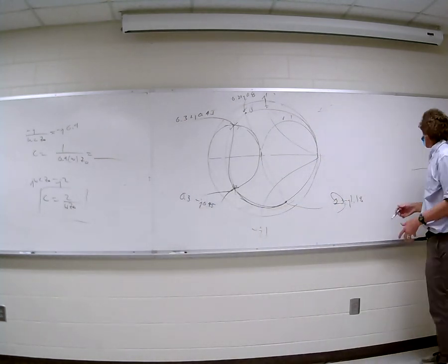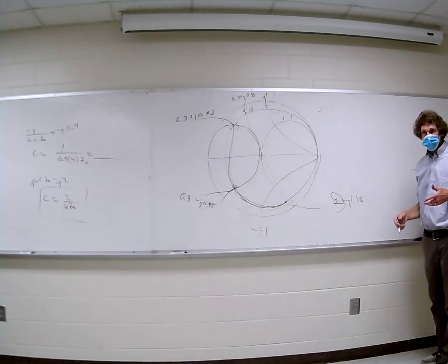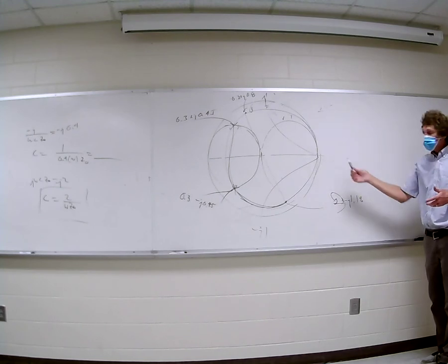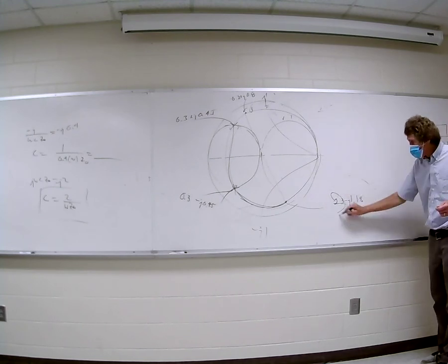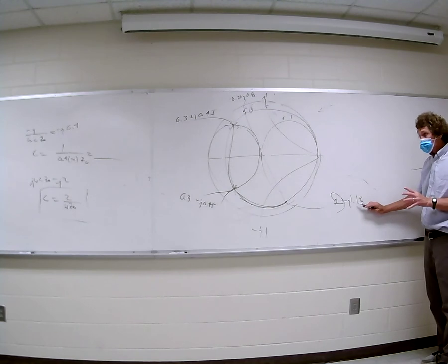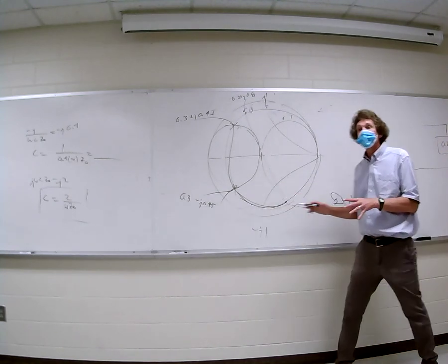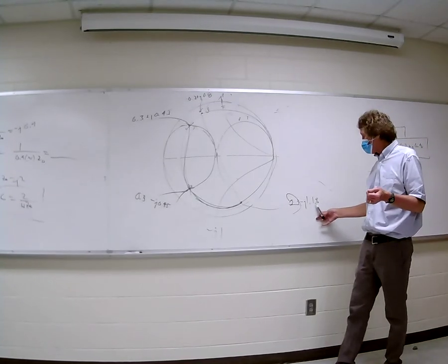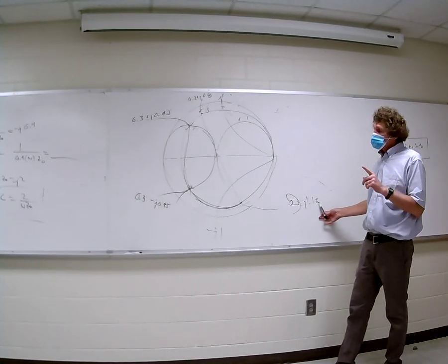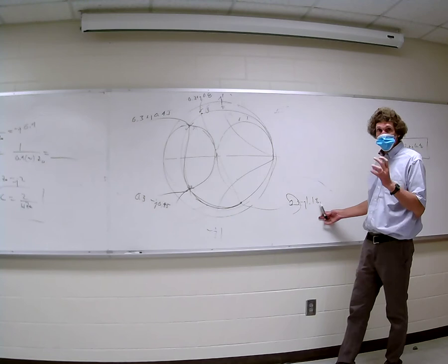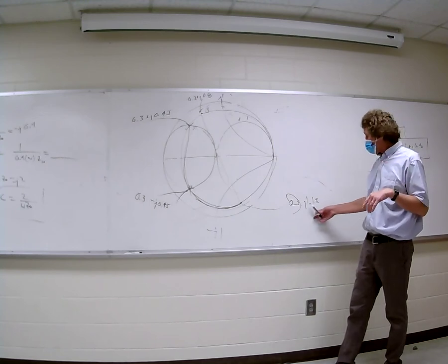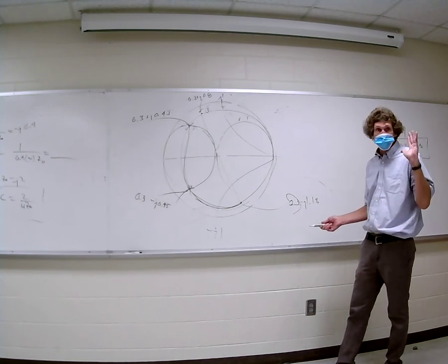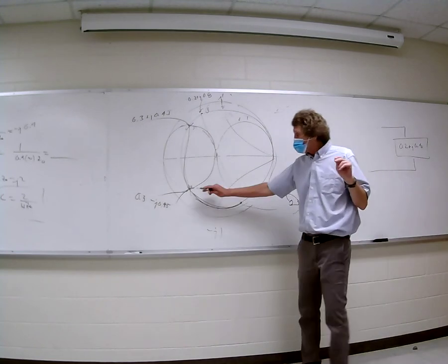All right, now here's my point. We're adding an admittance. Do you agree? Start with impedance. Now, if I add an admittance and get to this point right here, it would still be a capacitor, right? Because it's a positive value of j. I've got 1.18 negative. I want to get to 0.45 negative, so I subtract 0.45 from this, and that would be the amount of the positive j. That would land me here, correct?